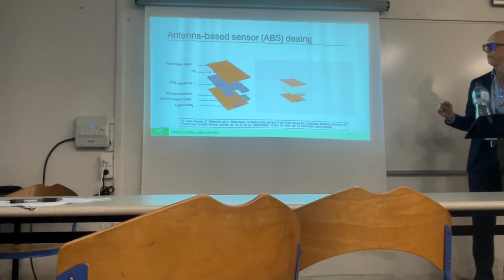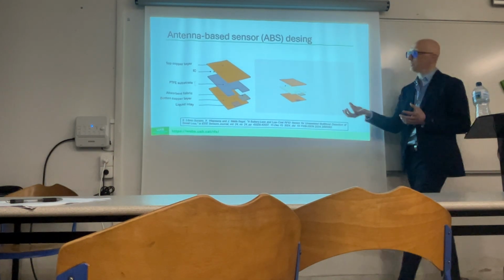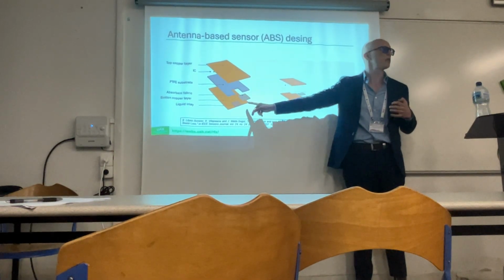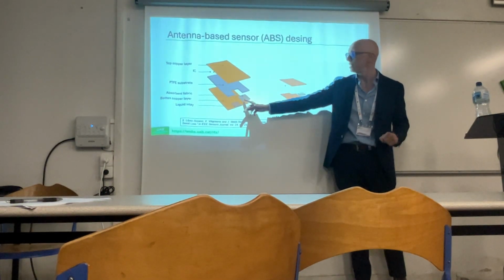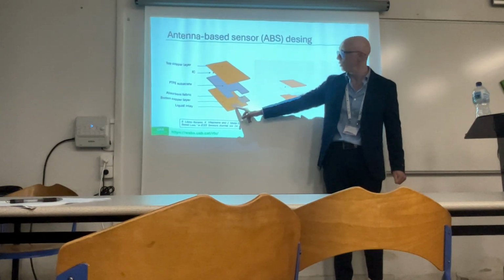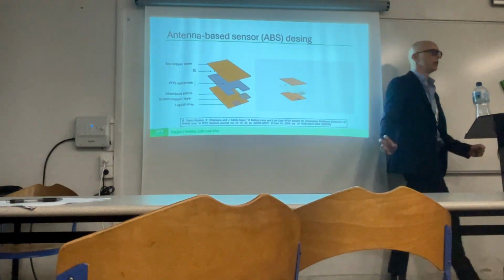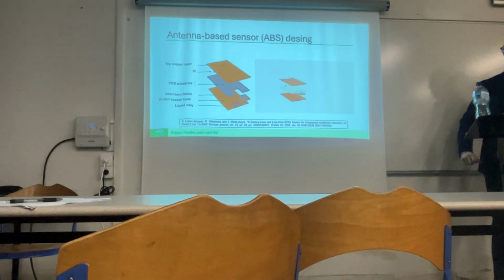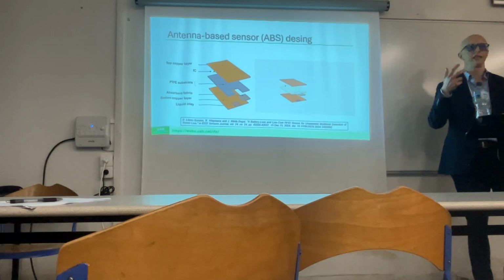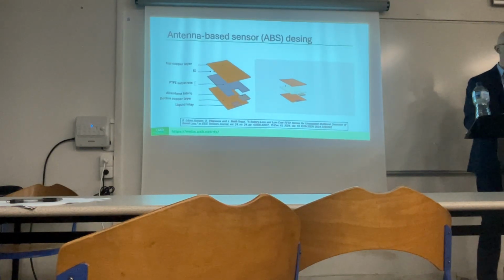So the Teflon substrate has been machined to embed an absorbent fabric patch which will contain the liquid, the water in this case, and an inlay of a network of holes has been opened in one of the bottom layers to allow for infusing the water or letting it evaporate during the drying process.